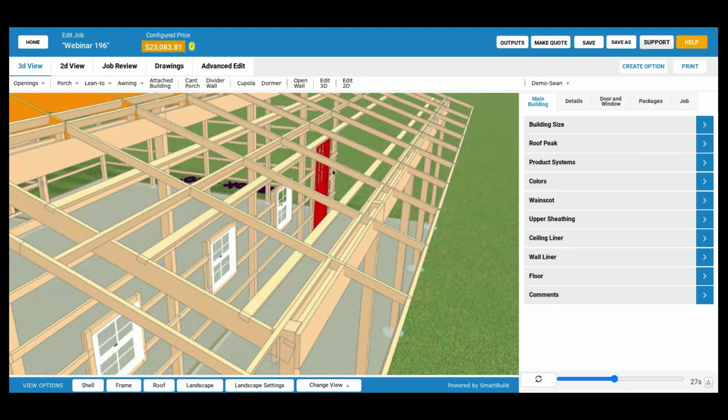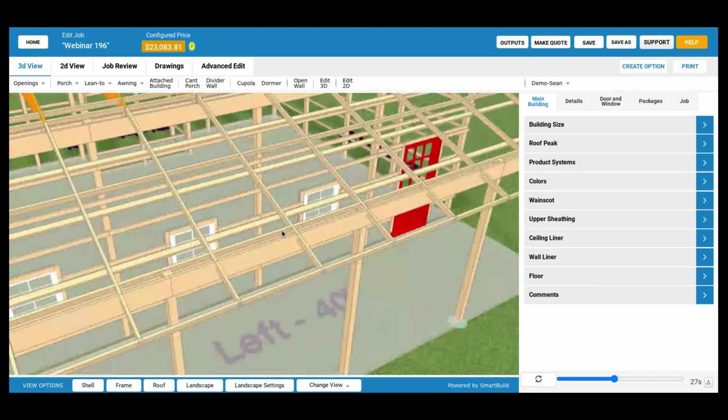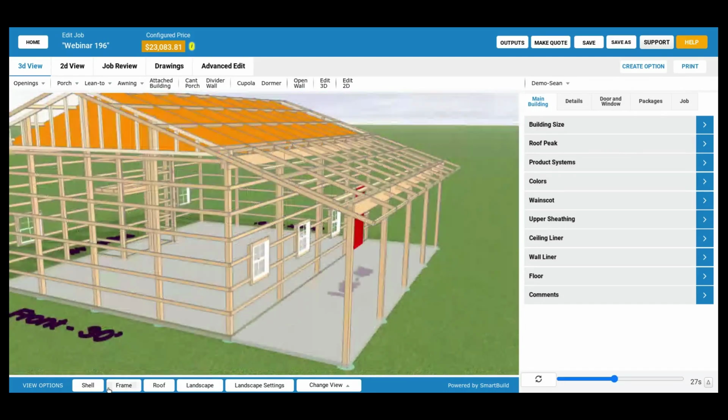So we've had requests that we just always want to take these outriggers up to the second purlin. So there's going to be some additional length on these purlins, and that's just the way it's going to be right now. It's going to go up to the second purlin. Again, it's one of those things, if we need to make additional tweaks or changes to those, let us know, but you should be seeing, if you're using these outriggers, that they'll extend up to the second purlin. A related change that's not on the porches, I think that's everything for the porches right now.